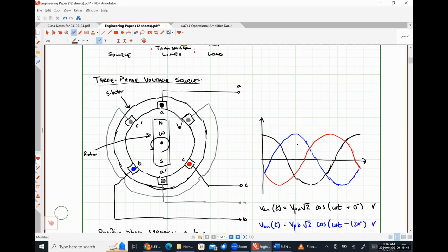Because if you just have a single commutator for positive and a single commutator piece for negative, it's going to act very jerkily because the voltage that's applied across the terminals is constantly experiencing a very large change. Whereas if you break your commutator up into like 60 pieces, it's going to see a small ripple.